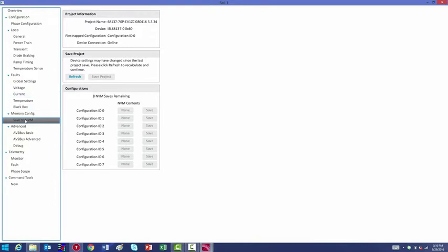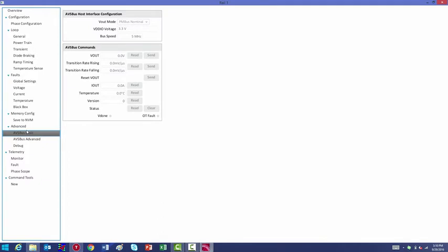The Rail Inspector tool also has advanced features like AVSBus. AVSBus is a fast point-to-point communication with up to 50 megahertz speeds. This allows the part to communicate with ASICs that support AVSBus interfaces in a very fast manner. With PowerNavigator, you can very quickly evaluate and demonstrate AVSBus and see the dynamic response behavior of the controller with an oscilloscope. The final page here is the telemetry page.